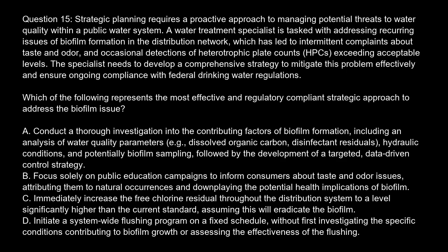Option A. Conduct a thorough investigation into the contributing factors of biofilm formation, including an analysis of water quality parameters, e.g., dissolved organic carbon, disinfectant residuals, hydraulic conditions, and potentially biofilm sampling, followed by the development of a targeted, data-driven control strategy. Option B. Focus solely on public education campaigns to inform consumers about taste and odor issues, attributing them to natural occurrences and downplaying the potential health implications of biofilm.